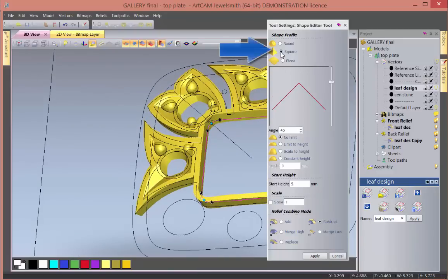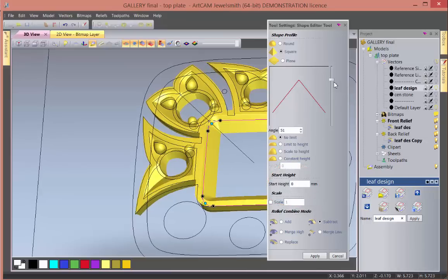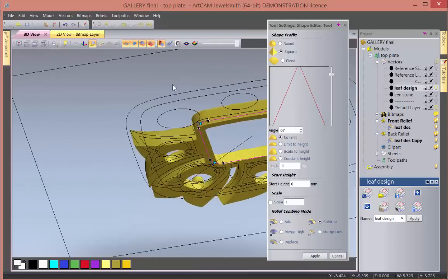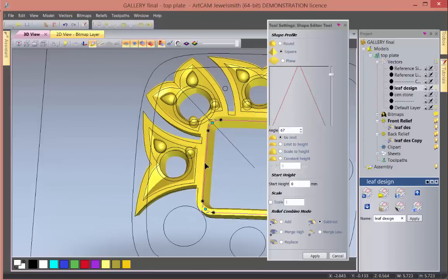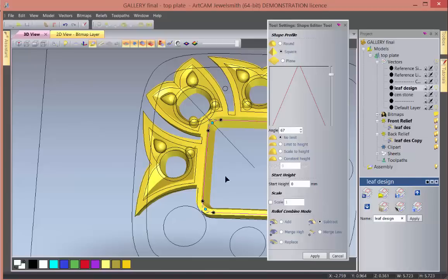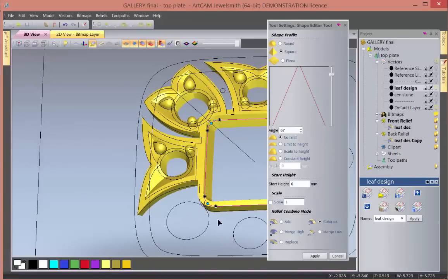If you want to put a slight taper on, you still can. Okay, so this once again will give you a surface. Let's put this onto 0 so you can see what's going on. This will give you a nice little cut straight down into the piece. Now this can go straight down or at an angle. It doesn't really matter because the center head will sit exactly over this. So this center head is going to be sitting over this trim work, and basically we're just making that actual trim work. If we're happy with this as it is, we're going to apply and cancel it out.